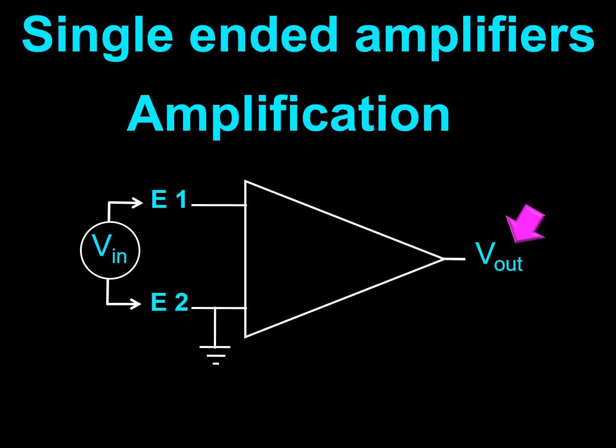On the other side of the frame, indicated by the arrow, is the voltage going out. In this frame, I have added a dashed line and connected it to the output of the amplifier. This line connecting the ground to the output is usually omitted in most representations of single-ended amplifiers, but it is understood that output voltage is also given in relation to the ground.